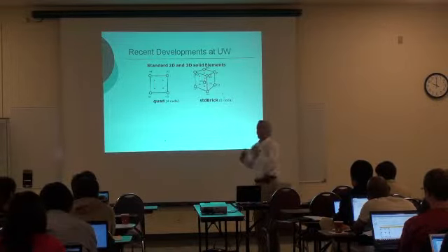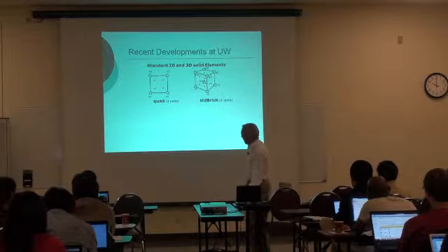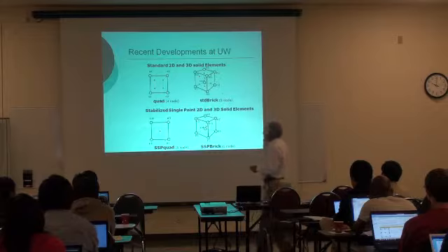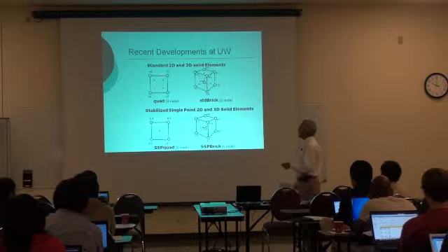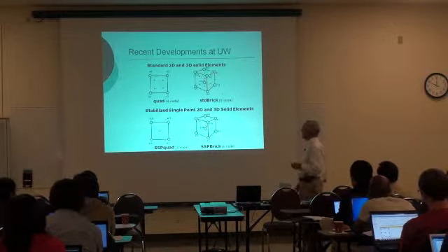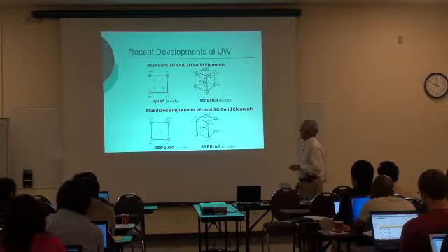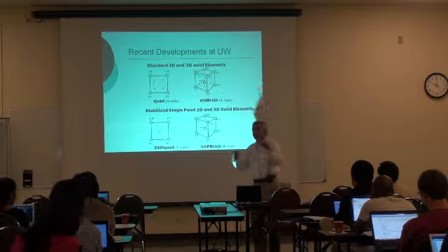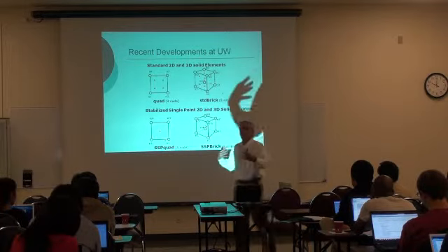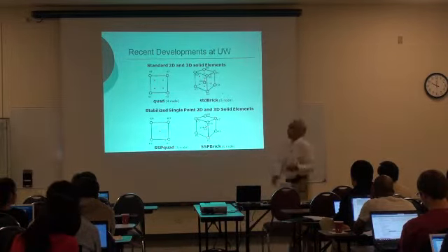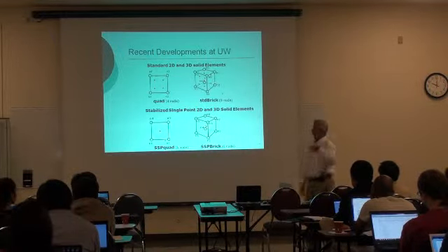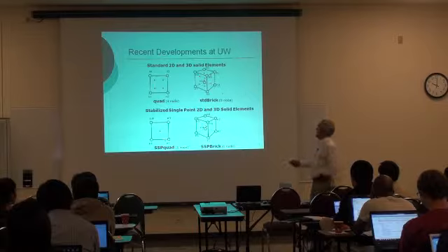I would say they are not as efficient as other formulations could be, in particular because of the number of Gauss points. So we have been looking at the possibility of using elements that have only 1 Gauss point instead of 4. That reduces the number of operations that you have to perform. Instead of performing all the operations at all the Gauss points, you perform the operations at only 1 Gauss point, both in the case of the 2D element and in the 3D element.